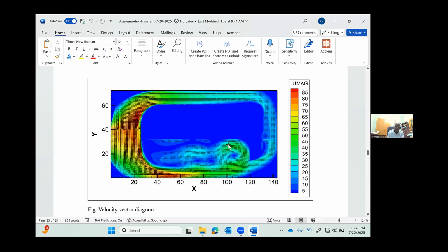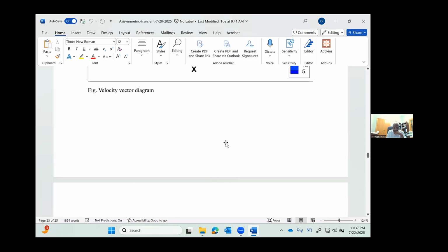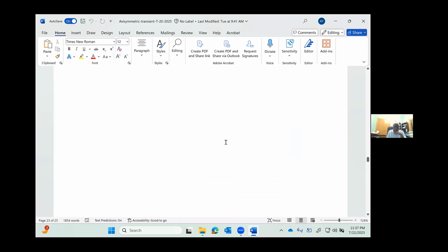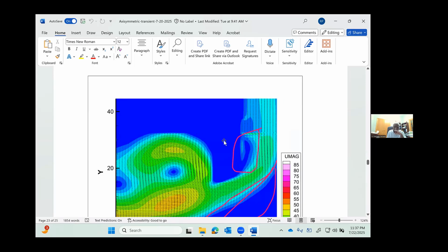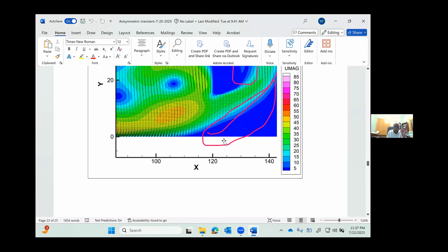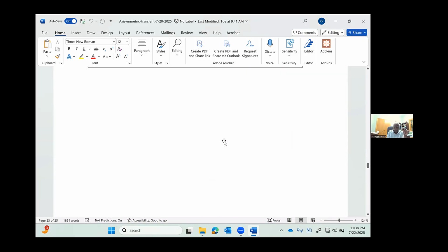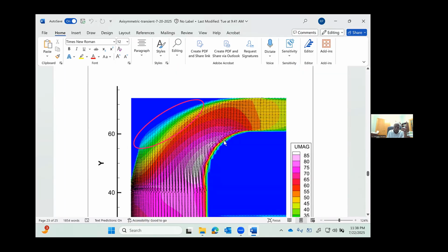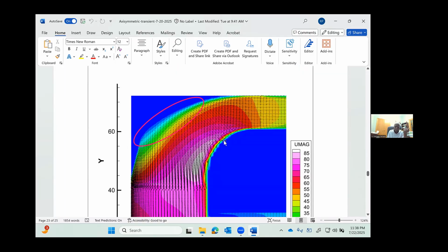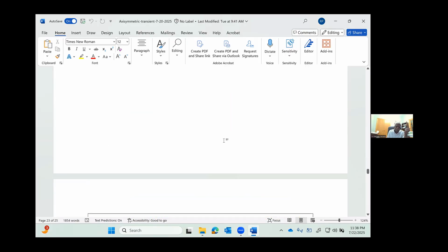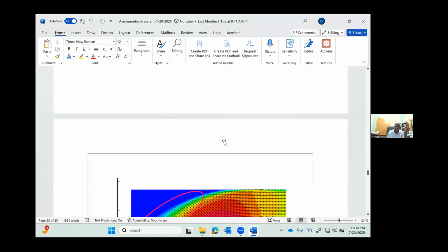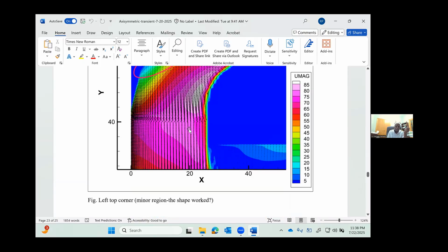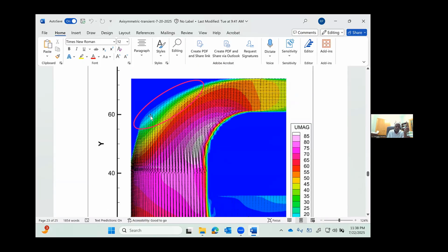We are helping them in the design. So you can see that unless you are able to make a proper design and proper grid resolutions, you are not going to capture all the flow features. So the grid is a very, very important issue, and you have to come up with something sophisticated. In this case, I try to manipulate it in such a way. I am using a rectangular grid system, and then I come up with a sophisticated way to remove all the curved places and other places where the geometry is not there.